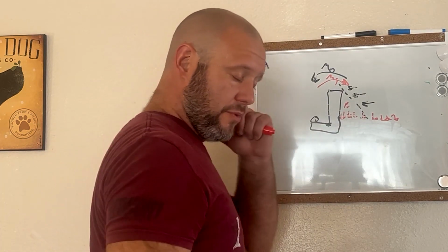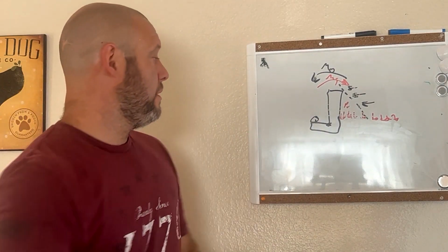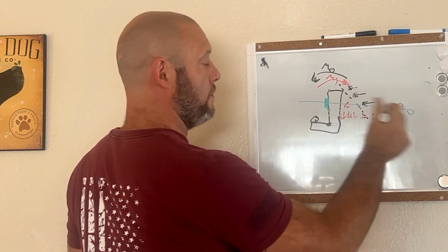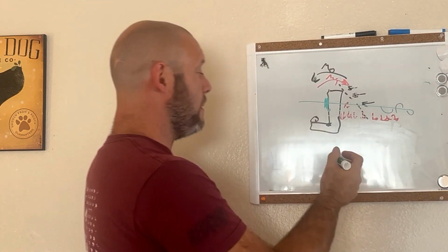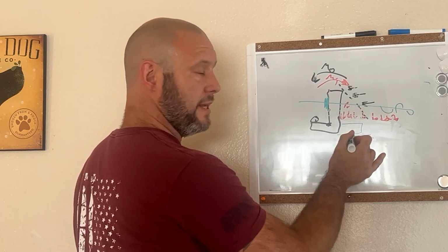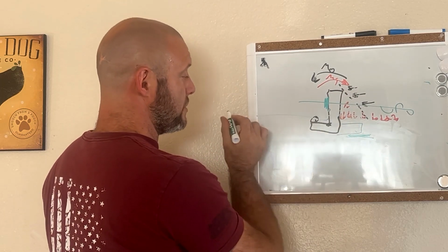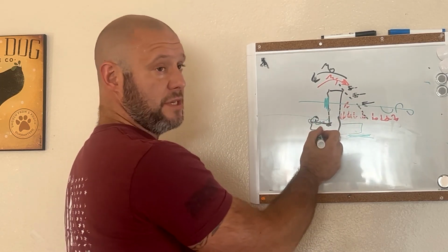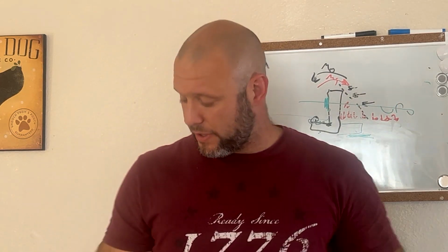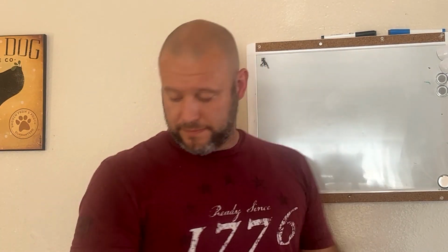If you're doing tieback anchors, where you put a wall plate here or an I-beam or something, and you run through with your anchors, right? And then when you tension it, you try to pull this thing back up. But if you have a footing down here and soil or anything has gotten in here, that's going to help resist the straightening moment, right? In kind, if you've got soil over here, that's going to help resist that too. So these are really good repairs, but it's impossible to figure out what type of failure you're experiencing without knowing exactly what you're looking at on a retaining wall.